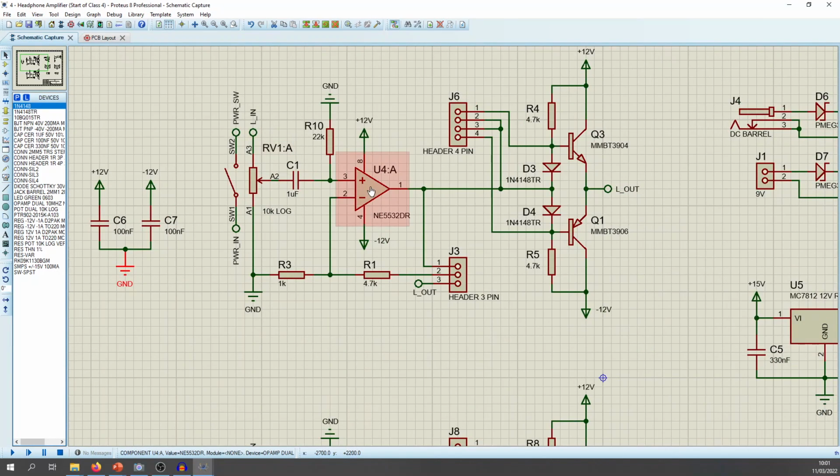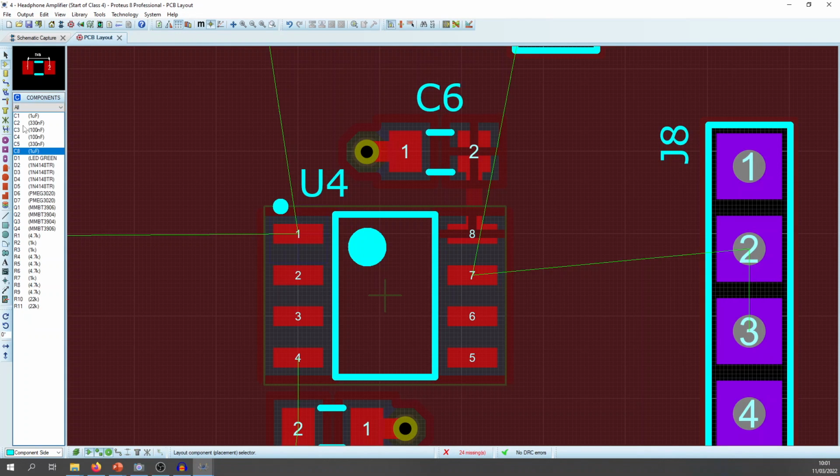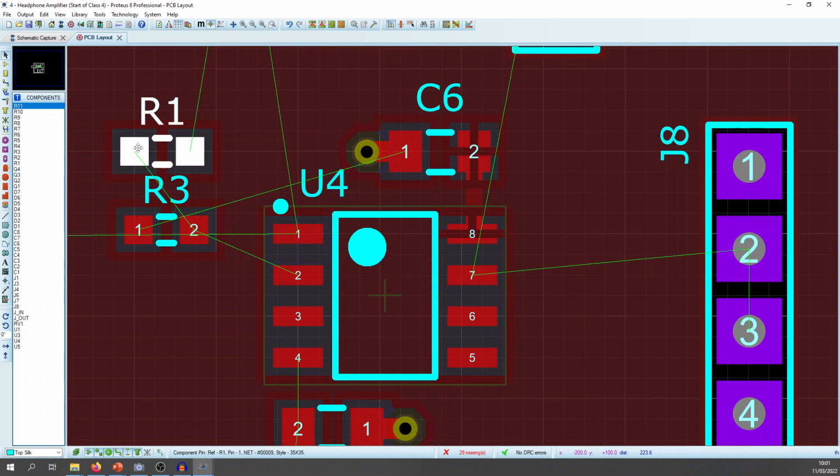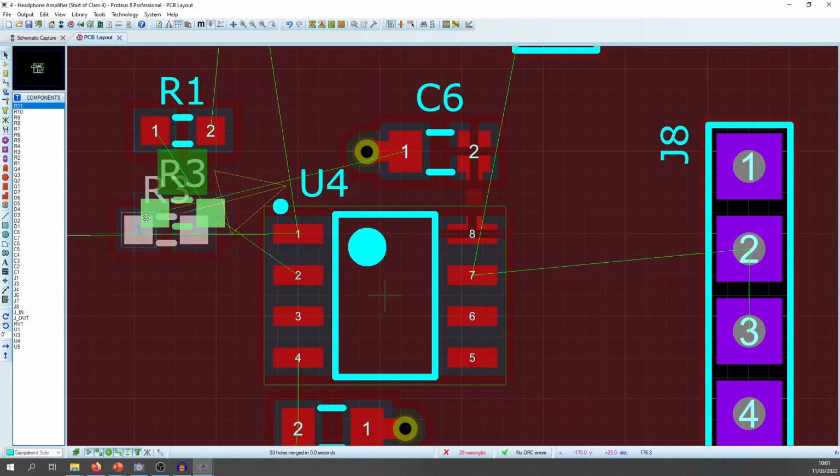So, as you said before, Parik, feedback path is really important. The feedback path of here is output through J3, R1 back in, and R3, we can place R3 close as well. So R1 and R3, I'm going to place them on the board. R1, R3. I'm going to change the grid snap to a bit slightly coarser, because we might not need such a fine snap.